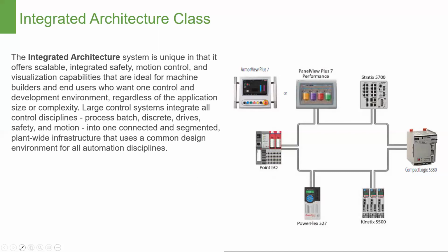There's always going to be a resource limit, no doubt, but it's not limited like the standard, where you can only have, I think, up to 100 displays in the application. And it supports a ring architecture as well as what we saw before, the linear and the star. So you can definitely integrate this right into your network and into the integrated architecture type class devices.